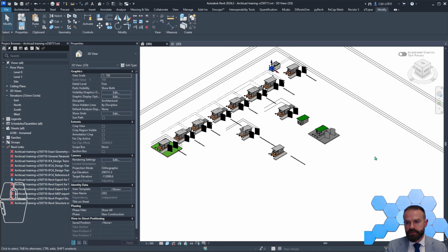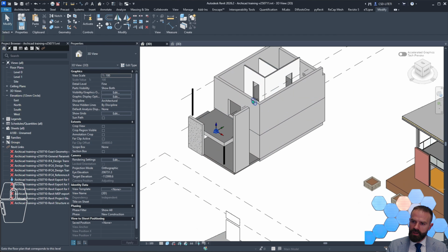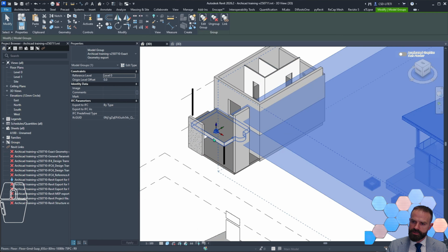Okay, so let's conclude all these interesting testing techniques. So first option, if you get IFC files from ArchiCAD, you can transform them inside Revit model using Advance Steel, and you will get editable objects.